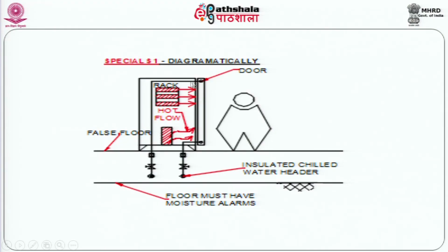Now this is a rack which you saw earlier. It has a door. This door will not only have side perforations, but by itself it is something like a eutectic pad. In other words, it is a device which is like a refrigerator door, thick and solid, but it admits cold water to go inside. This cold water keeps this panel very cold, and this draws out the return water. That means water can be injected at, let us say, about 12 degrees centigrade. It goes in and returns at about 18 degrees centigrade.